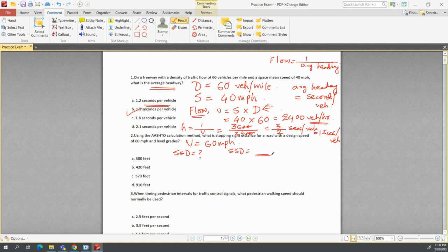The first part is how much time the driver takes to realize and start the action of the brake. Like, first the driver needs to put on the brake. That is the first part of this equation. The first term is V times t, where t is the perception time. I'm just writing the formula here, which we have converted with 1.47 into V times t, because we put V in miles per hour and you get SSD in feet. That's why we have multiplied it by 1.47.